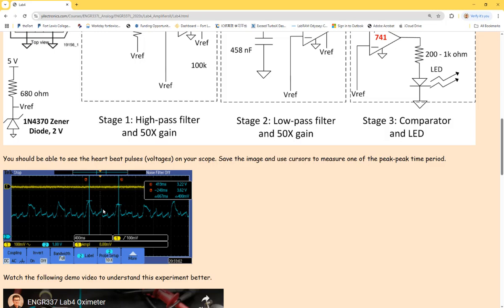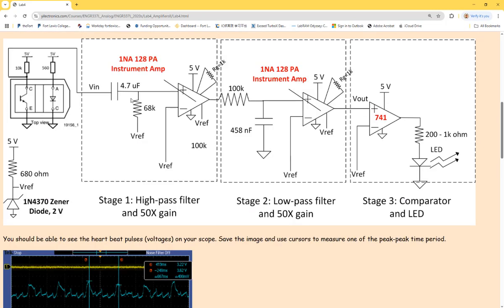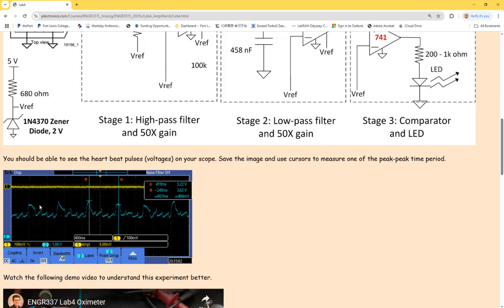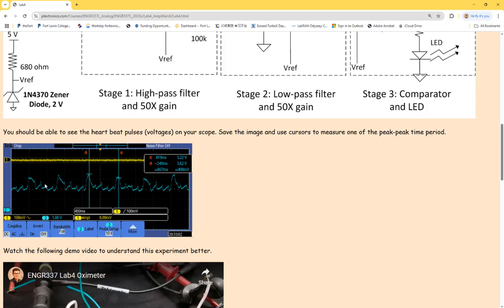Keep in mind, this is a super, super important point as an electrical engineer when you are trying to design something, okay? In the senior seminar, I saw people who don't even know there's a random DC offset, directly shorting that analog signal into the ADC and trying to make it work. That definitely will not work, because all these analog sensors give you some random DC offset. If you look at this one, this is a 0 base point. Eventually, it's being lifted by some random DC offset.